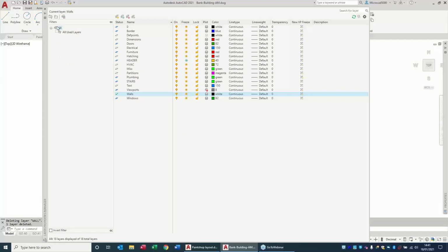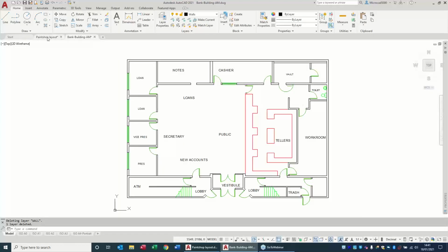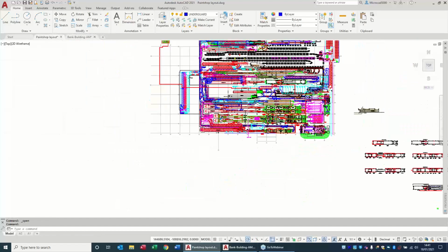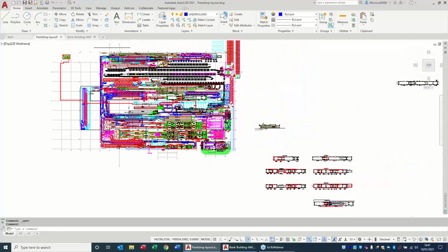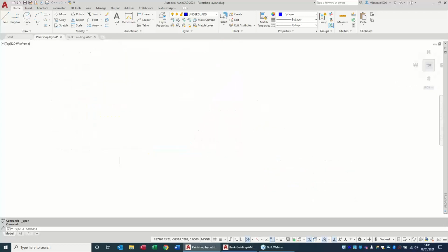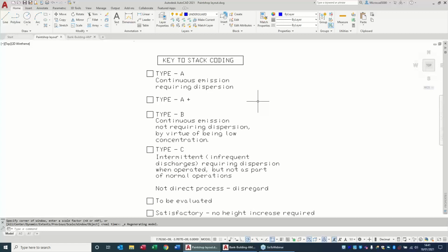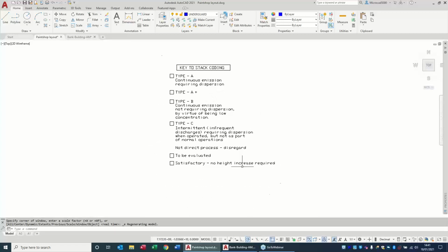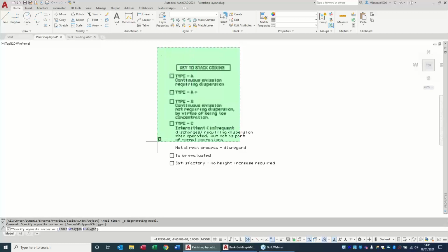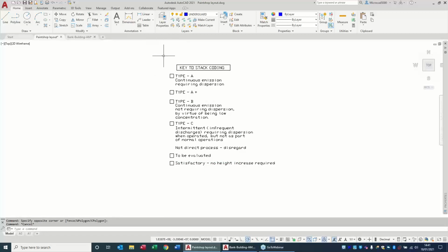Right, I'm going to have a look at layer filters now. Layer filters, that's this column here. So let me go back to the paint shop layout drawing here, this one here. Now, if I double click my roller in this drawing file, it will do a zoom extents. It's brought up this massive text in the drawing file. The drawing itself, that drawing we were just looking at a moment ago, is that one pixel lit up there. See this? Can hardly see it. So I have to be really careful when I'm going to delete.